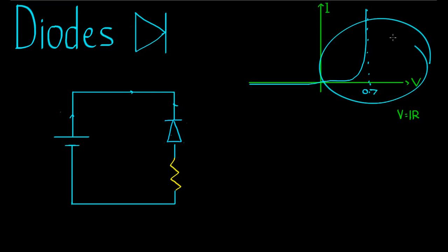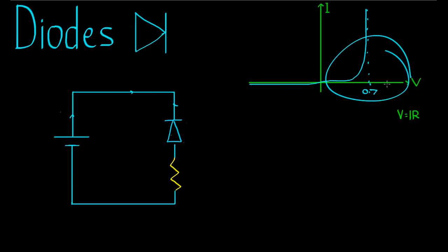Notice the diode in forward bias has no problem letting a lot of current through. But in reverse bias, it's not the voltage it's worried about, it's the current. So think forward bias, it's obsessed with the voltage it wants. In reverse bias, it's obsessed with the current it wants, and that current is effectively zero. In reverse bias, you can also think of it as just another resistor, but with a resistance of, say, 10,000 ohms, something very, very large. That's just a tip if you're ever trying to work out how a circuit would behave with the diode in